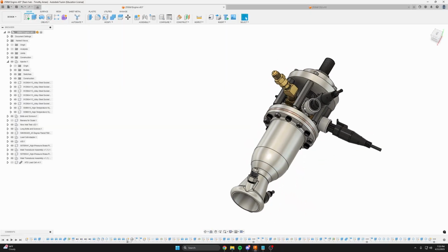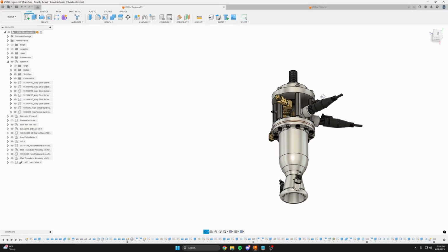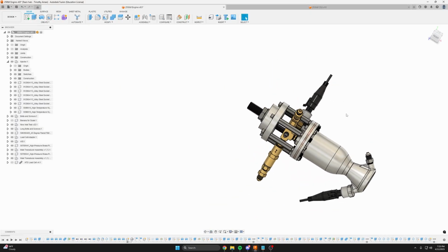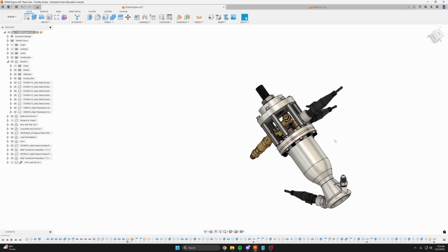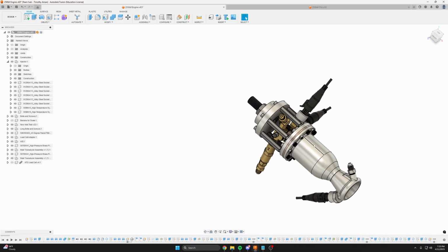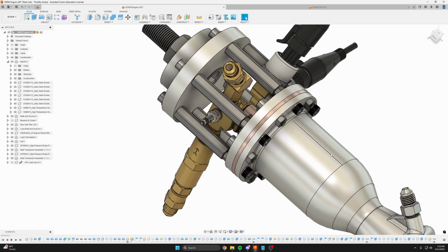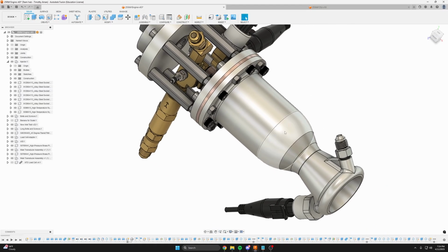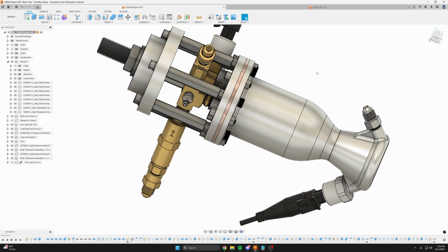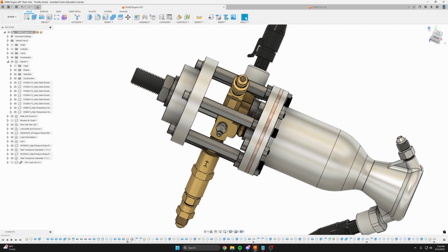And then you can see we have some pressure transducers here as well to take other pressure readings of the fluids at various stages. You can also add thermocouples, which we have elected not to do. But with metal printing, you could easily add a bunch of ports along the cooling channels if you wanted to take some thermocouple or pressure readings at various stages. You could get a lot of good data out of that. Cheap metal printing really unlocks a lot here.